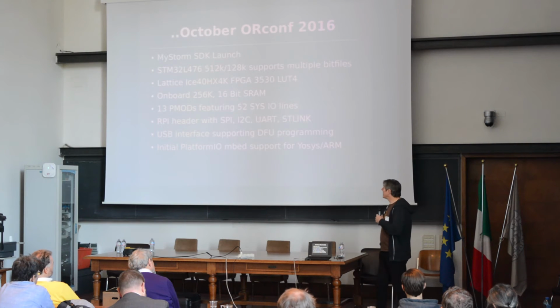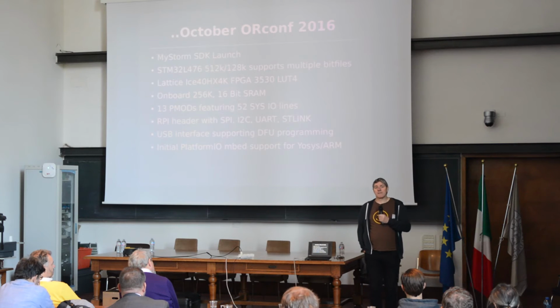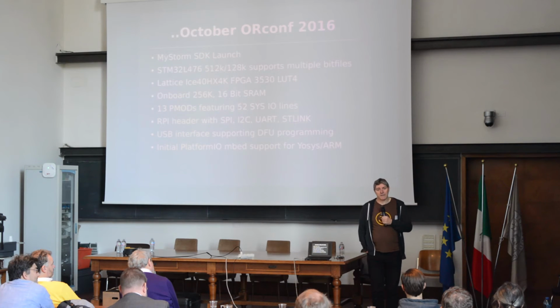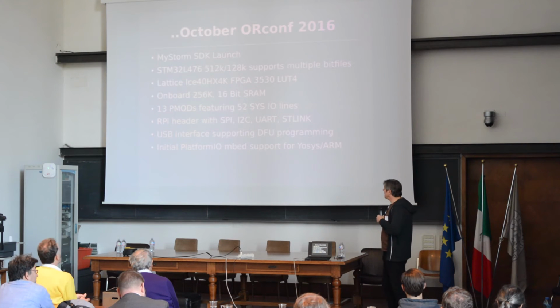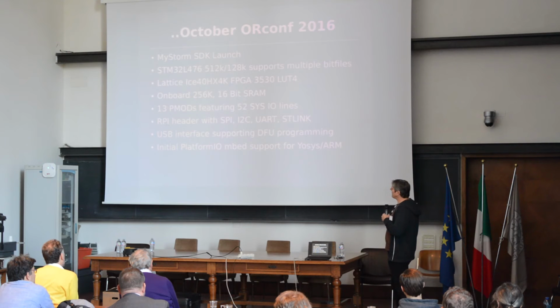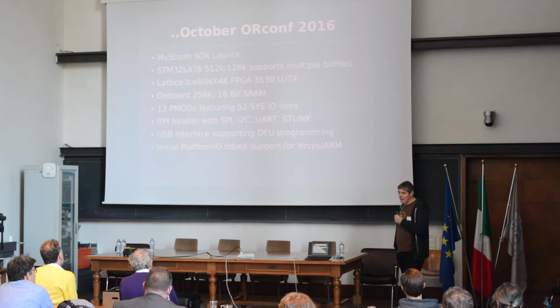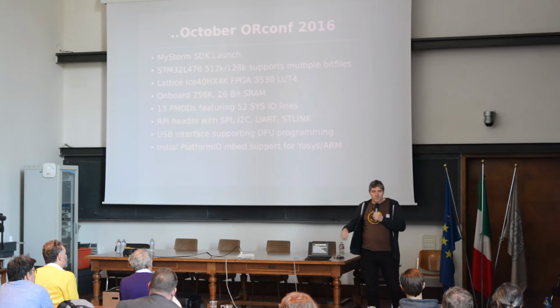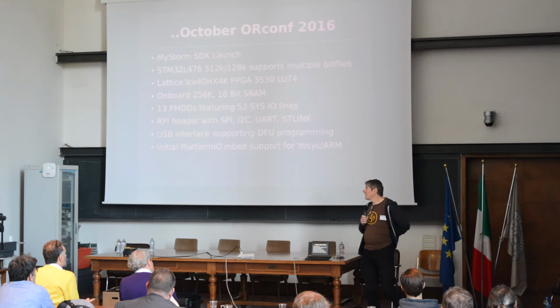So we thought we wanted to do something a bit more special for the software developers and hardware developers out there that we wanted to get these boards out to first. So we went a little bit over the top and chose basically one of the best ones that we could get, which was an STM32L476. Now the 476 is an M4 rather than an M3, so you have a floating point unit built in.